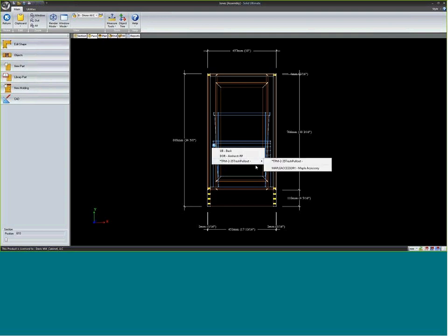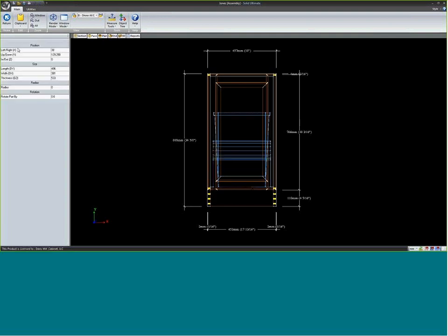So what I'm going to do is go to this trash pullout, and notice X, Y, and Z, dy, dx, dz. So X, Y, and Z are my relative location of the trash bin container with respect to the next step up the hierarchy, or this cabinet container. So it's telling me I'm 30 millimeters away from the left side, the left-right X. Again, you see it down here in this icon.